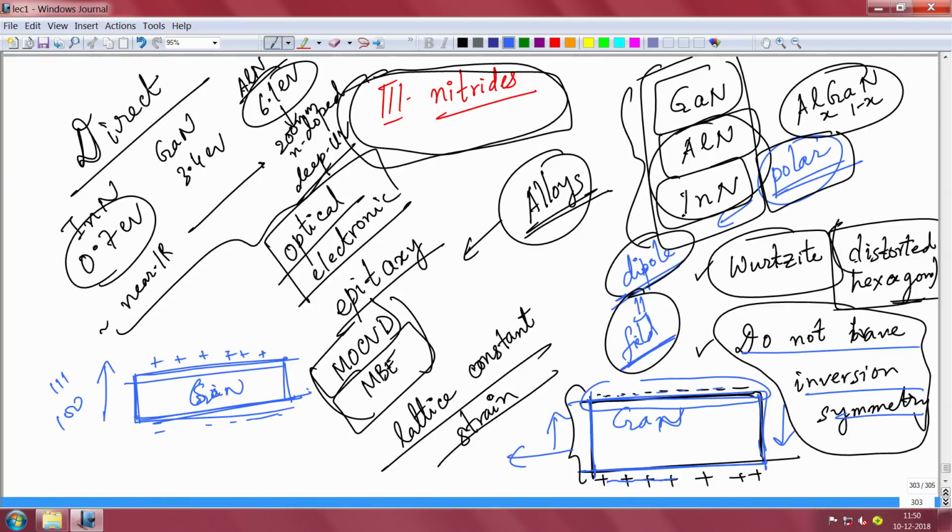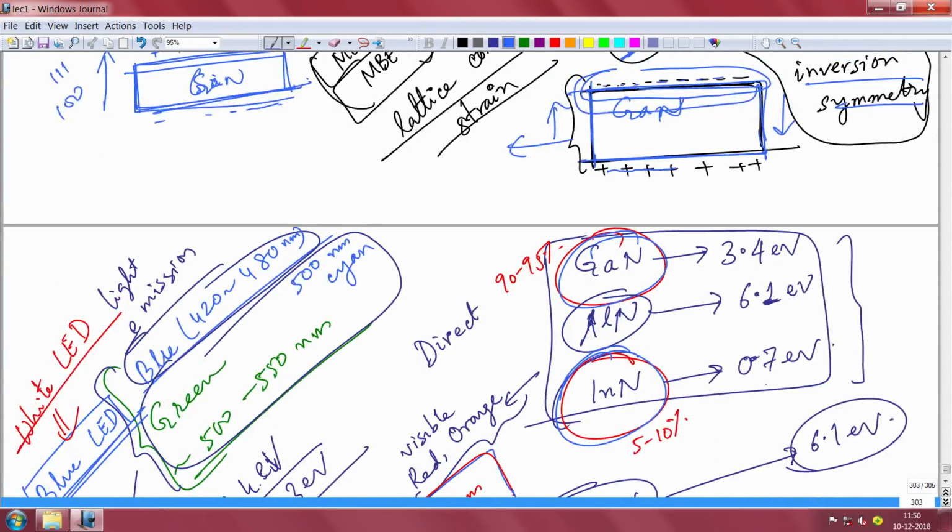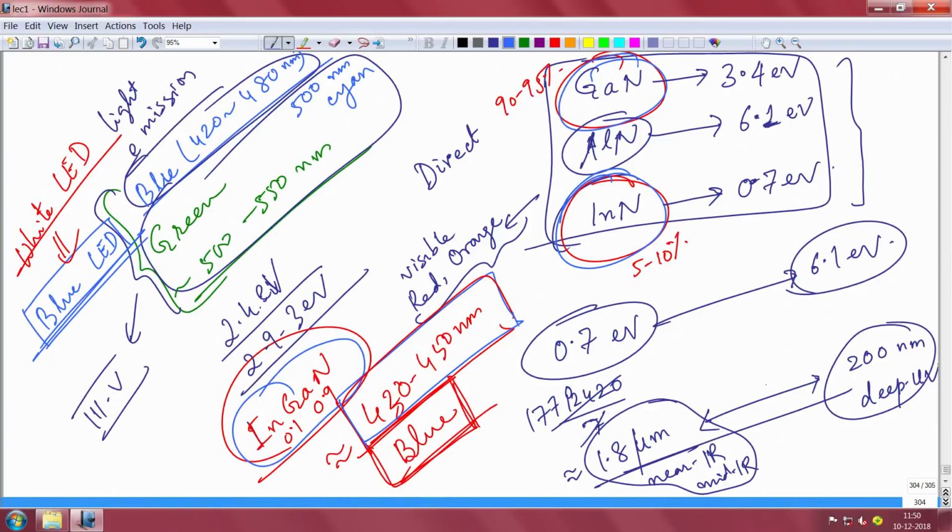I told you this is not present in many of the other common semiconductors like silicon and gallium arsenide and other things. And apart from this polarization, gallium nitride has a huge range of band gap, as I told you. So this makes it very unique, and it has a lot of material properties which cannot be found in other systems, and you will see why heterostructures based on this are unique, because now they are polar, they have an inbuilt field. So even if you are applying an electric field outside, you will see a very strange kind of band diagram here. Okay, so that's what I told you.